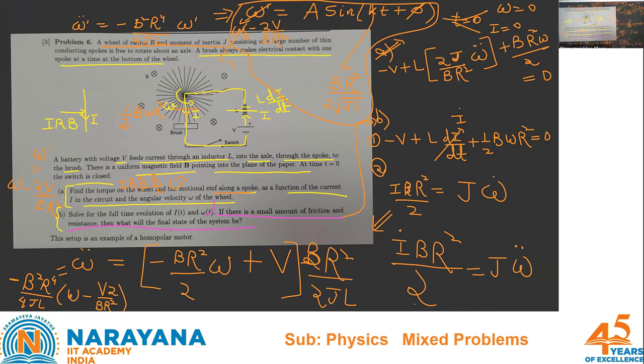If this is the system and the system has got a small resistance, then in the final state, what can we comment upon? Current and omega. And there is a concept of back EMF that we can use here. I'm making two comments and think about it. The thing is, this EMF which you are generating, that half b omega r square, in the final state, it seems to balance V. So as far as the final omega is concerned, it becomes 2V upon BR square, right?